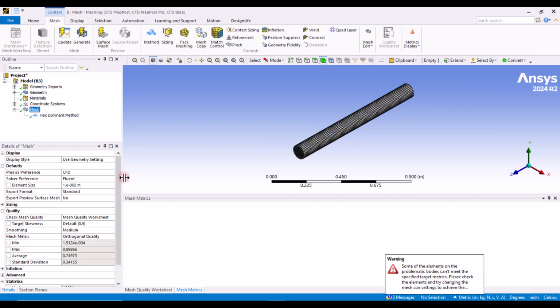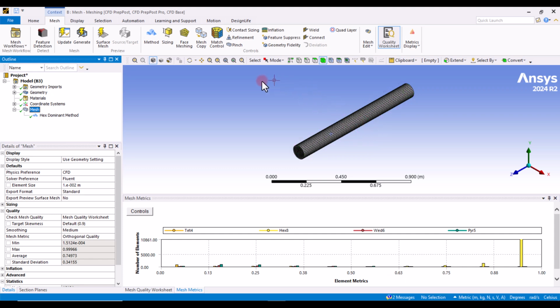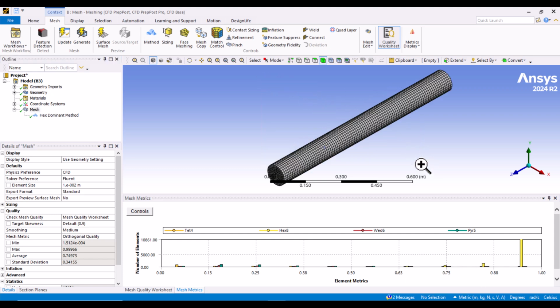Very well. So as you can see, we have a great mesh using hexagonal cells, as can be seen from the outside view. But the point is that as you check the quality regarding the orthogonal quality, you can see what's going inside. As shown in here, we have the minimum orthogonal quality of 0, which is a poor mesh, and it just somehow guarantees that.